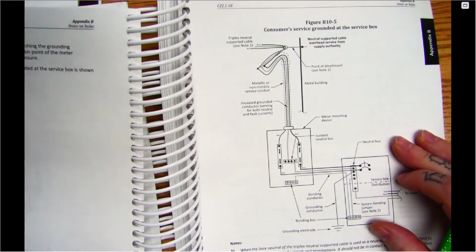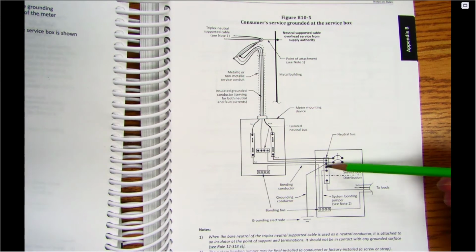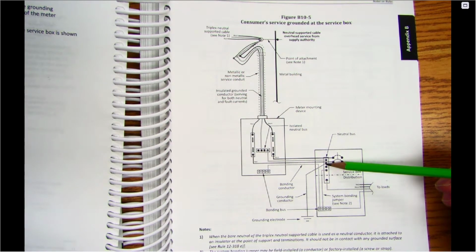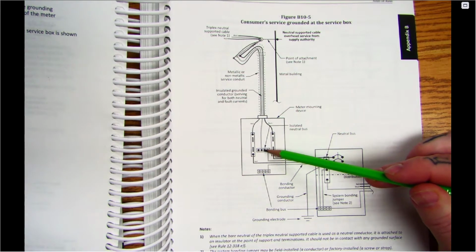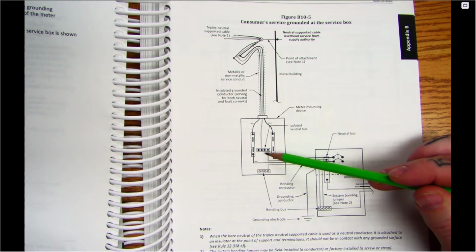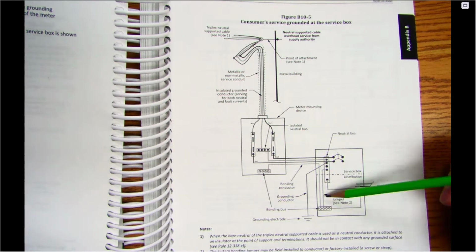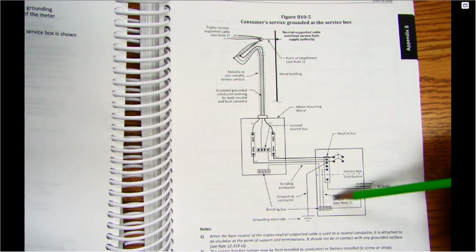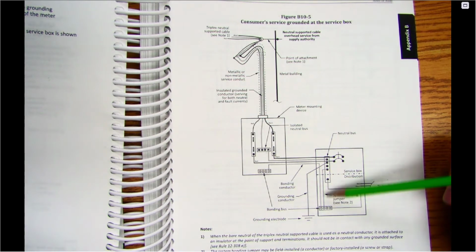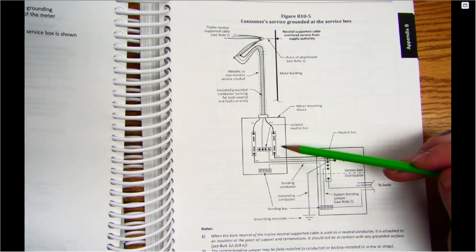Okay, and then they talk about the other scenario, and they do in your module too, but this picture's right on the next page. This is where we're grounding it in the service box instead. And still, one connection at the grounded circuit. So when we go back here, again, now we're isolated here. So if there was a screw, we'd take it out there. Our system bonding jumper now is happening in this portion here because this is where the grounding is taking place. Then we have our system bond, still referred to as a system bond because it's where our grounding is taking place for our system. Then we carry a bond back so that this enclosure is bonded.